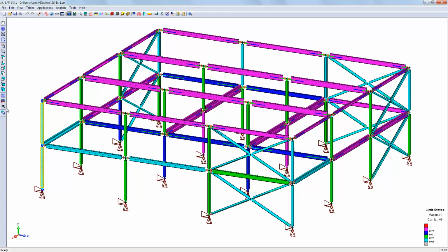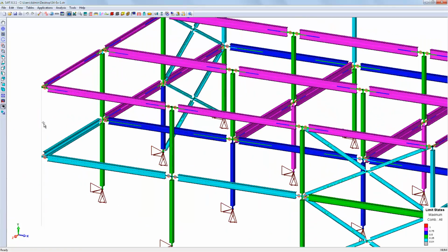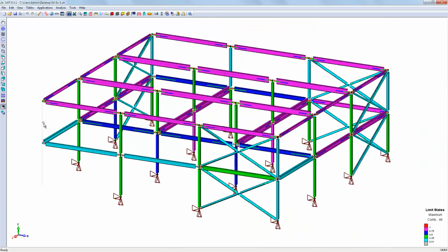The Dim Selected command allows you to dim all elements of the structure that are currently selected. When the command is activated, all visible elements of the structure that are currently selected are dimmed. No graphical operation may be performed on dimmed elements. Note that the dimmed elements are automatically removed from the current selection.